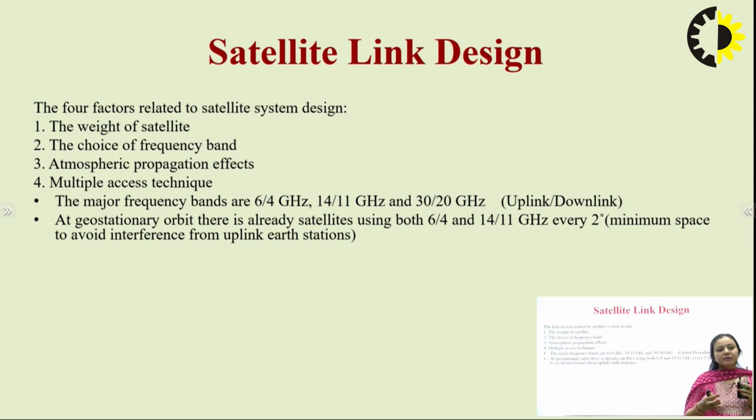Wherever we have mentioned two frequencies, it's not that you divide them and get some number. The first frequency represents the uplink frequency and the second one represents the downlink frequency. As we are already aware, the uplink and downlink frequencies are different to avoid any kind of interference. So we can have these three common frequency bands.